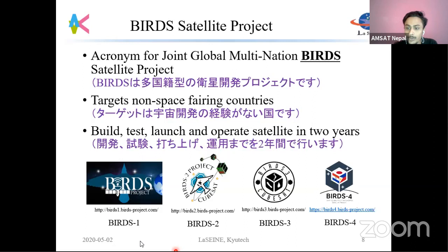One more question: do you route the PCBs in Eagle with the auto router or do you route them yourself? Also, there are two crystals in an STM32 microcontroller, one for high frequency and one for low frequency. What are the differences, and why are two different frequencies used in those microcontrollers? You mean the frequency at which you run the microcontroller? Yeah, exactly, the oscillating frequency. Well, frequency directly relates to the power consumption. If you lower the frequency, you consume less power. If you raise the frequency, you use more power. If you need real time, really quick data, then you need to increase the frequency. That's the only thing I see.